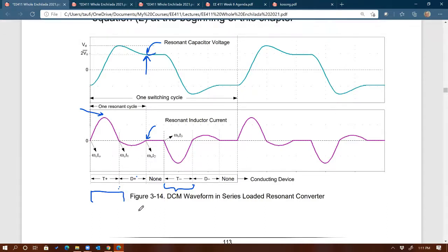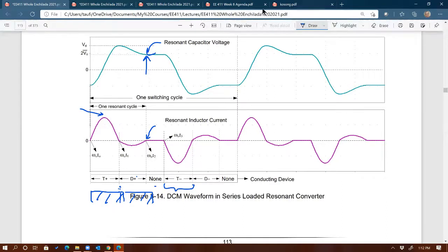But even if you have some error, that negative voltage will help. You just have to make sure it stays off after that diode stops conducting. Yeah, exactly. So as long as you turn off the MOSFET right after D plus is conducting, then you're fine. Don't extend the gate pulse of the MOSFET to be above T2 like this. That's not good. That's not going to make this circuit work properly.